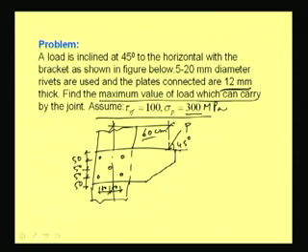So, what we have to do? We have to find out the rivet which is carrying the maximum load, then we have to equalize it, right. We can find out the maximum force in terms of P which is coming to a particular rivet, and in which rivet it is coming, that also we can find out, then we can make it equal and then we can find out the values, right.